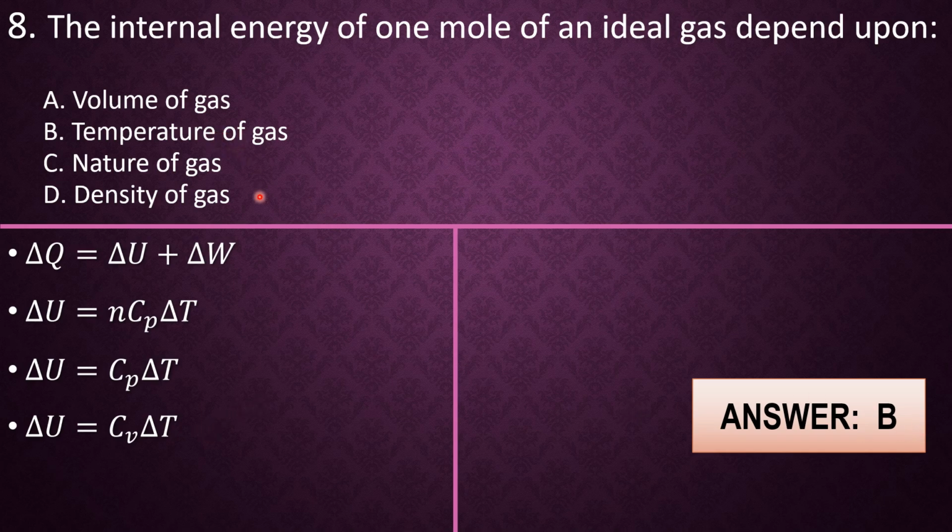And that's why for isothermal thermodynamic processes, you notice that the temperature is constant, and so the change in internal energy for such processes is 0. So du is always 0 for such processes. So dq is always dw. The heat supplied basically goes in to enable the gas to do work, right, for isothermal processes.